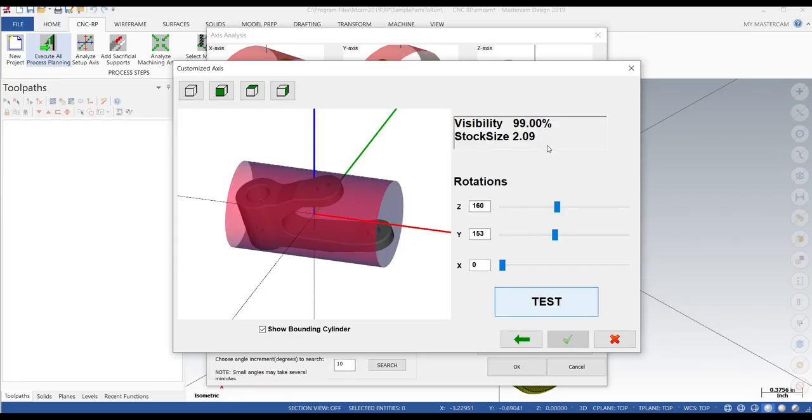A word of warning: when you machine off of the normal degree axes, for instance, like machining away from 0, 45, 90 degrees, your part geometry can become less precise, and for many parts, it will not work as well to machine at these weird degree angles, like 160 and 153. So most of the time, you're going to want to stay on your more fixed angles, your 0, your 45, just to make it easier and faster for your part to be created.